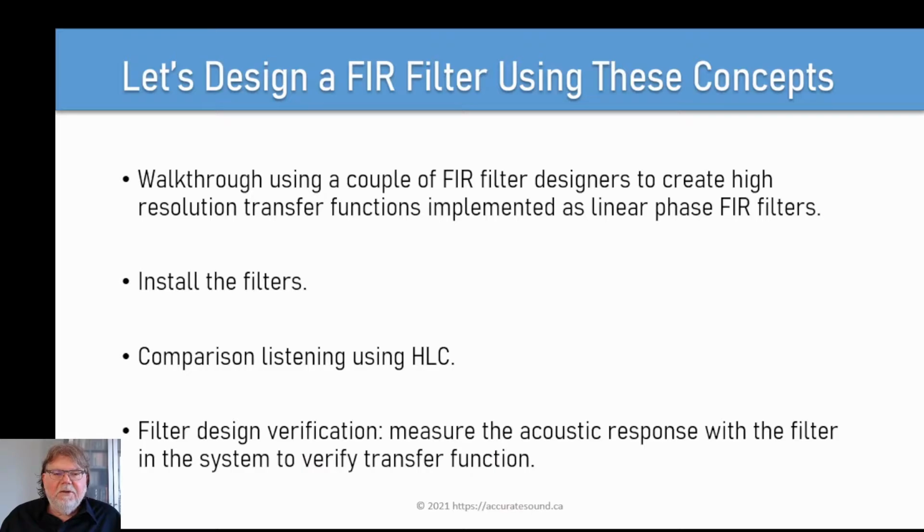So let's design a FIR filter using these concepts. I'm going to walk through a couple of FIR filter designers to create some high-resolution transfer functions and implement them as linear phase FIR filters. We're going to install the filters. We're going to do some comparison listening, because I think it's really important that people understand that there's a particular way that we need to actually compare filter A versus filter B, and that'll become clear once we get to that part. Once we've got through the listening section, we're going to look at the filter design verification. We're going to measure the acoustic response with the filter in the system to verify that the transfer function works as intended, as designed.